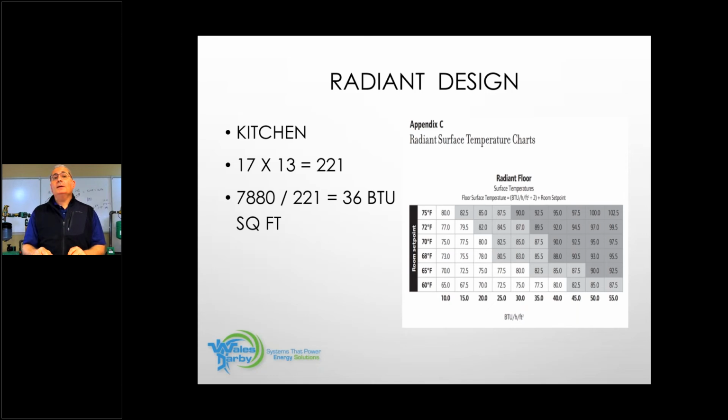For tile, we can go to a surface temperature of 85 degrees. If we go above that, gentlemen, your feet start to sweat, and they'll start to sweat right through your shoes. And I've experienced that. I've gone on jobs where they weren't controlled properly. People were complaining, and the moment you walked into the room, your feet started to sweat. So if I sold them a comfort system and I'm not delivering that comfort, that's a problem.